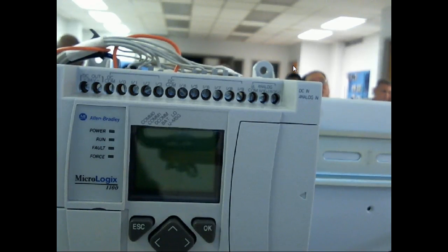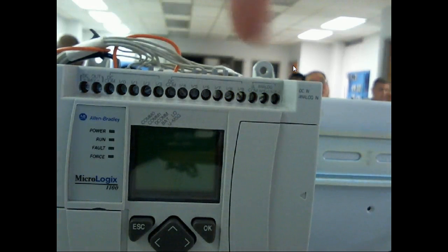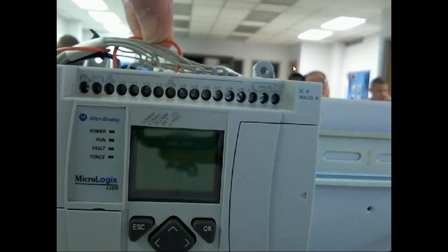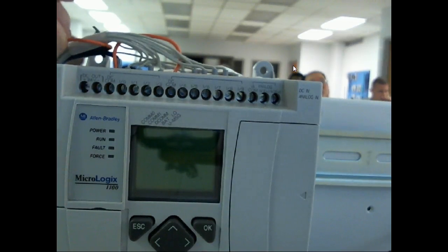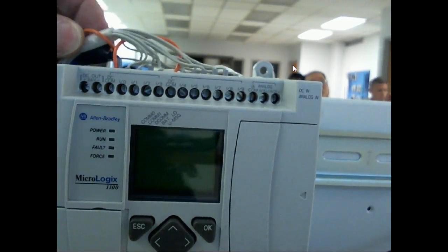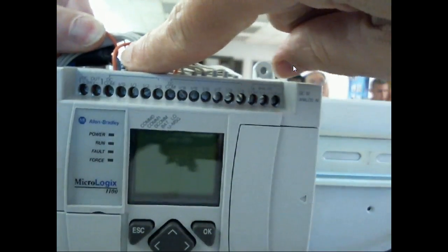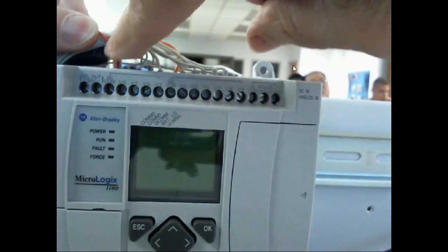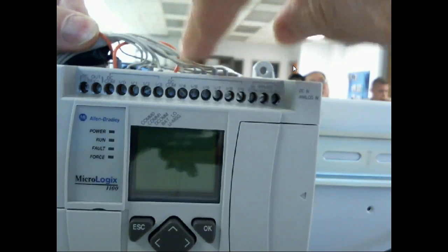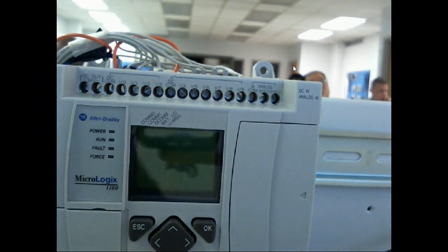Allen-Bradley's good at that. Well, they let you decide. If I just hook a minus to both of them, which you can see I got a jumper right here. So here's my minus coming in on this blue wire, and what I do is I just jump them together. So I'm putting minus, so I've got my input set up to sync. Are we okay? That makes sense.